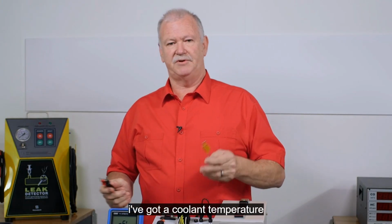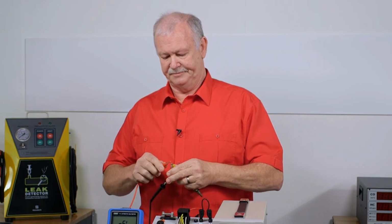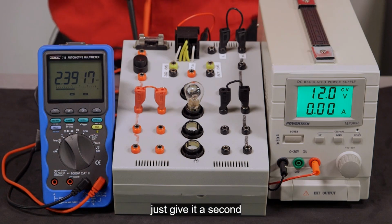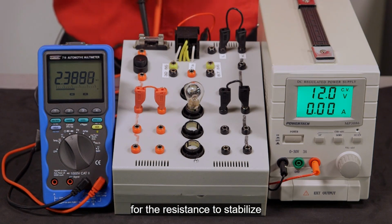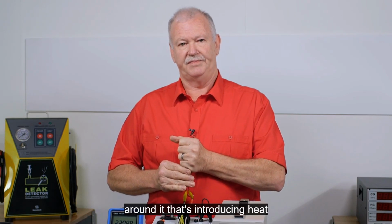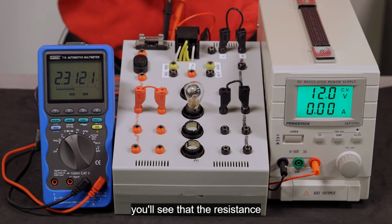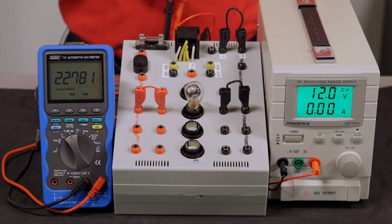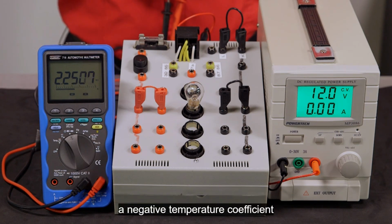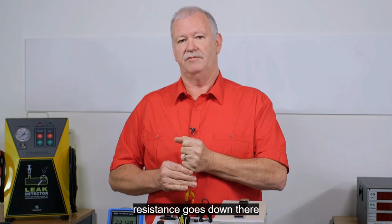And I've got a coolant temperature sensor, which I'll hook up to the meter. Just give it a second for the resistance to stabilise. I'll put my hand around it. That's introducing heat into the sensor, and you'll see that the resistance is starting to drop. This is an NTC device, a negative temperature coefficient. When temperature goes up, resistance goes down.